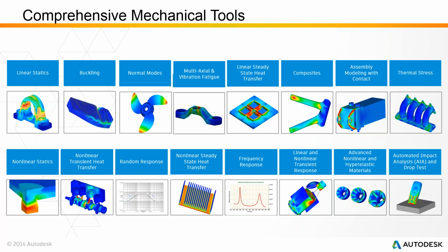You can also apply vibration and frequencies, and in the next release coming out very shortly, we can also apply shock responses like earthquakes, wind loads for example, to your designs and see how they respond in terms of stress and strains and deflections. As I mentioned, we can do fatigue analysis, so how many cycles to failure, particularly if your design is receiving cyclic loading. You can do thermal analysis, this could be steady state or transient, where the temperature loads can change with time.